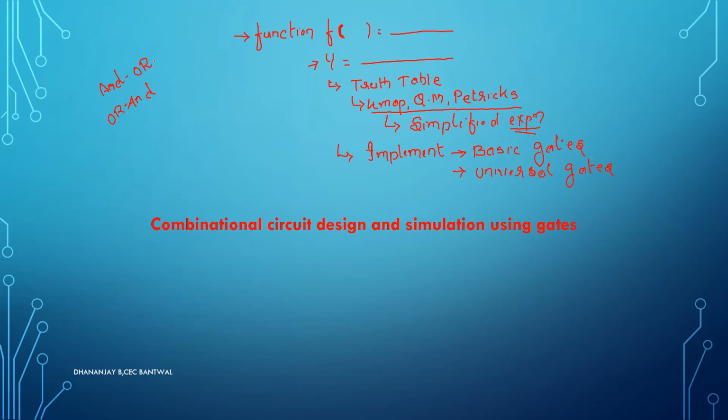This AND-OR combination circuit occurs if I am using the SOP method. Suppose you want to rig up the circuit using OR-AND, that is, inputs given to OR gates and the output obtained from the AND gate, then I will be going with the POS method. I do agree that both will have NOT gates in case they are needed. If the NOT gates are needed, I'll be embedding them in the circuit as needed.